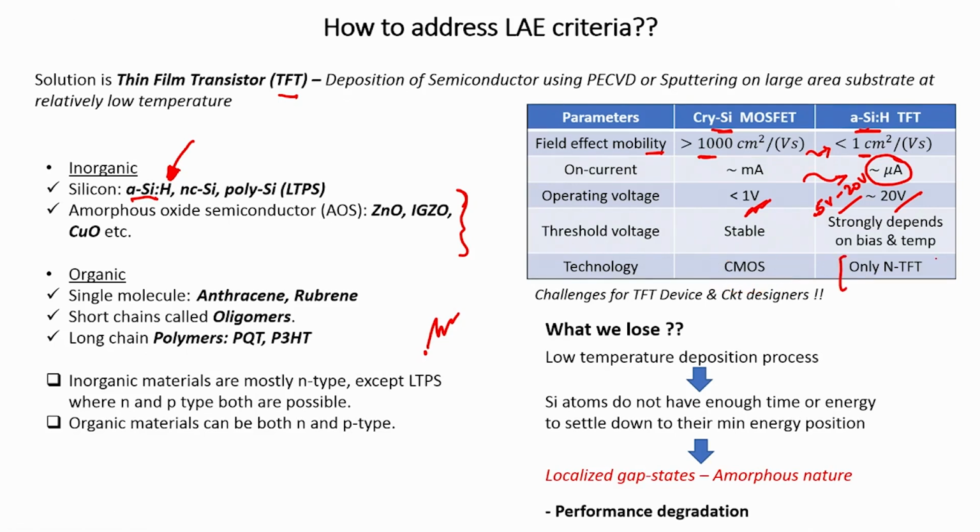Whereas in the case of amorphous semiconductors, most of the time, practically speaking, we only have N type transistors or only P type transistors. Most of the organics give you P type transistors, and amorphous silicon for example gives you N type behavior, so we do not have complementary MOS transistors in most materials. But having said that, there are also several organic materials that allow you to have both N and P type transistors, which means you do have a CMOS process in these materials.